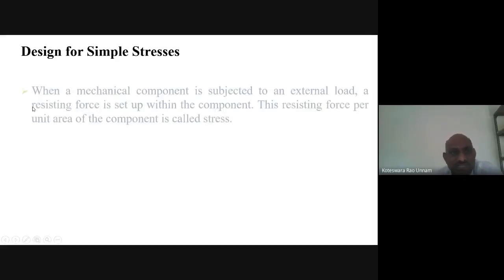that means if there is only one kind of stress, only normal stress or only shear stress or only bending stress, then we call them simple stresses. If there is a combination of stresses, say both bending stress as well as shear stress, then I can call that a complex stress system. We'll consider that complex system later. Now we see in case of simple stresses how we can compute the stress values. In that, first we'll consider the normal stress.